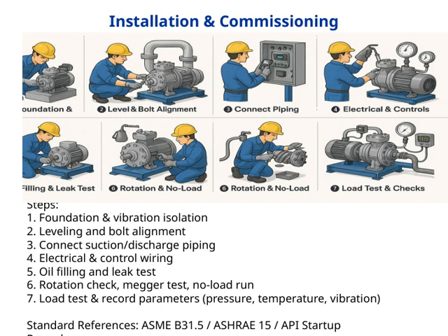Following that, we conduct a rotation check, perform a Megger test, and run the equipment without load to verify everything is functioning correctly before applying any operational load. Finally, we carry out a load test, during which we record key parameters like pressure, temperature, and vibration. This comprehensive testing ensures the system operates efficiently and reliably.